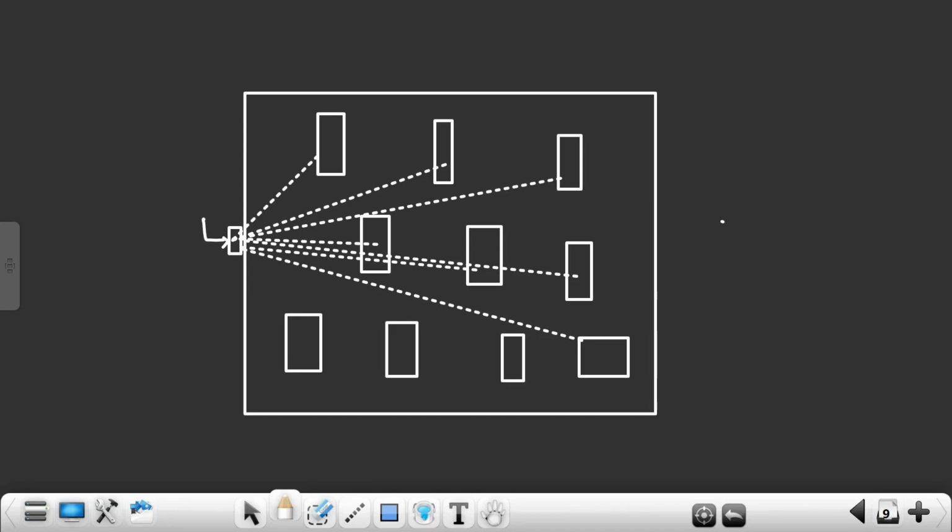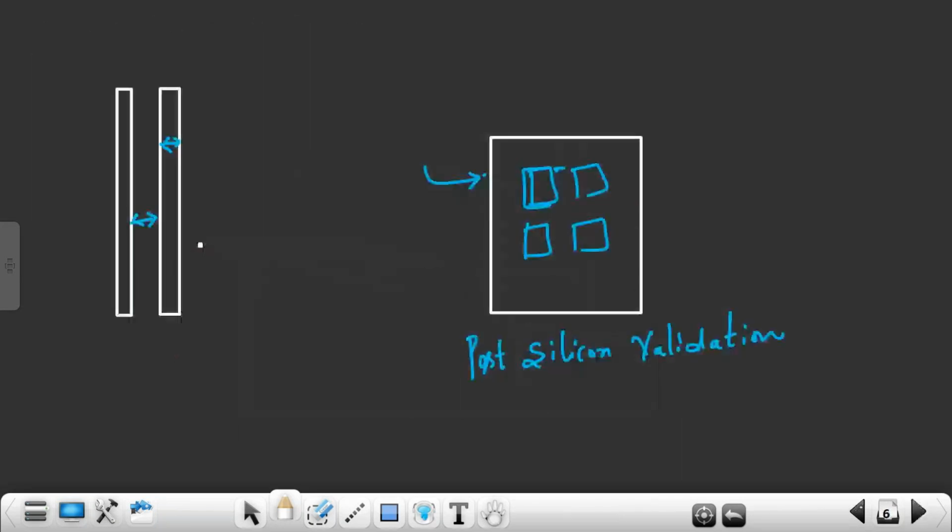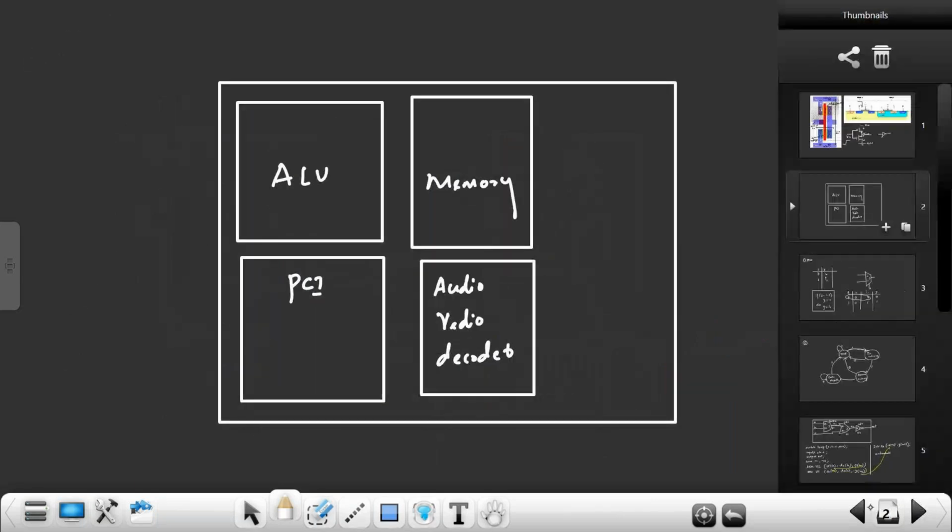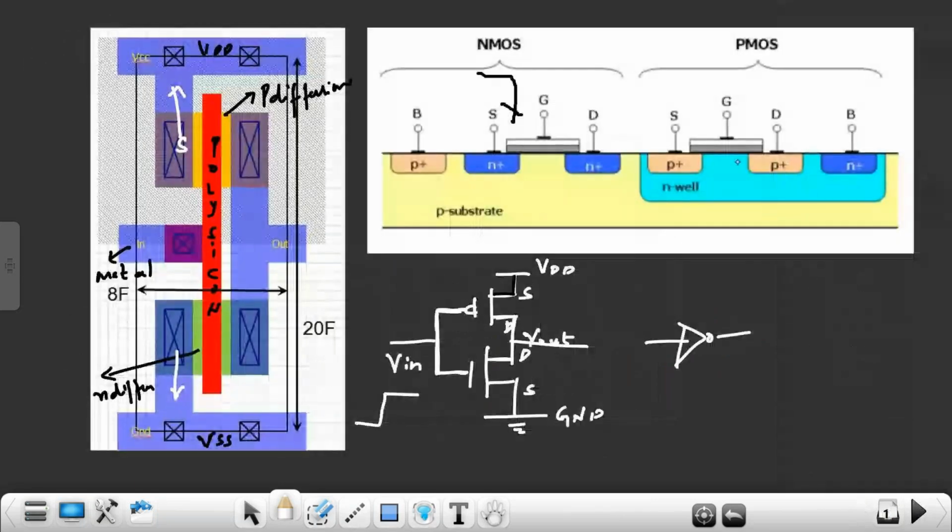See the load on this port. The capacitive load on this port gets increased. See, all these flip-flops will be having pin capacitance. See, flip-flop means input, right? Input is having pin capacitance. If you see this CMOS structure, you have a capacitance here. On top you have what? Positive plate.